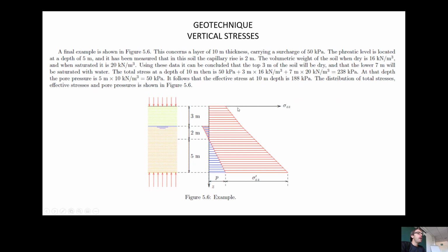but in this diagram, if we want to be honest, there is this part. This part is what I said, something that we neglect, but it exists. So it means that there is a part of the soil that entered in tension. As I said, this is not really considered in general, as an approximation, and especially in this course we don't pay particular attention because, as I said, soil is a material that cannot have tensile forces.